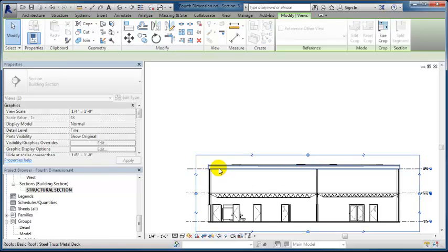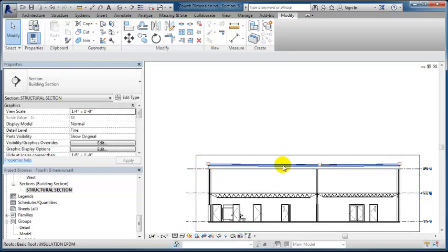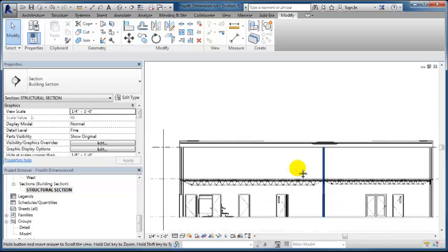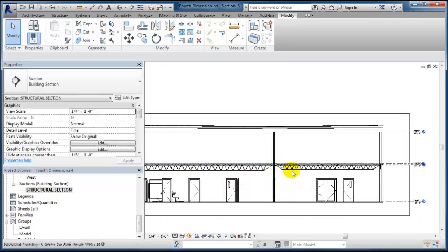If we wanted to, we could create a curb sweep that would go around the outside of the building and add that as well. So now we've basically added a second floor, a mezzanine level, and we end up having the first floor, and we have some real structural elements in here. So that's kind of what I wanted to show you how to do, how we could add those structural elements in there. Kind of a long video, but there you have it.